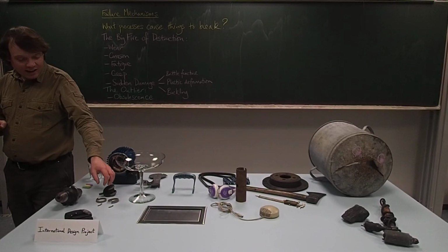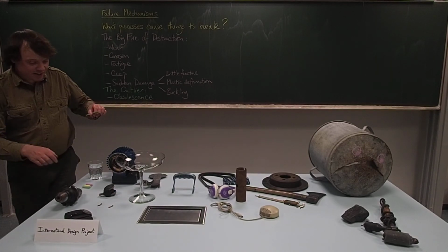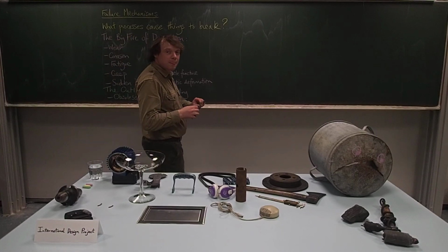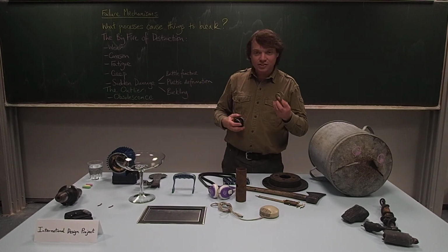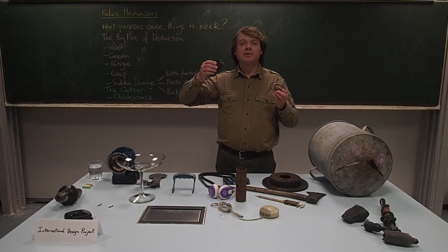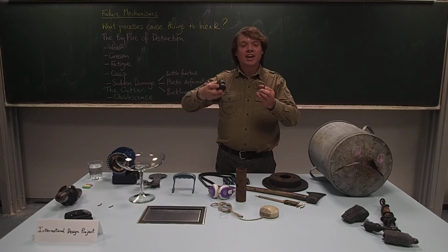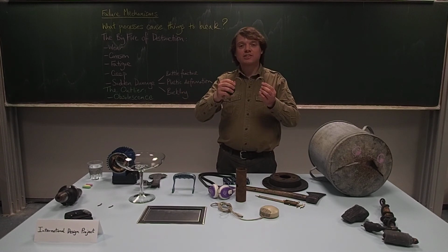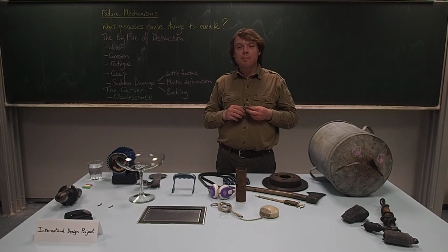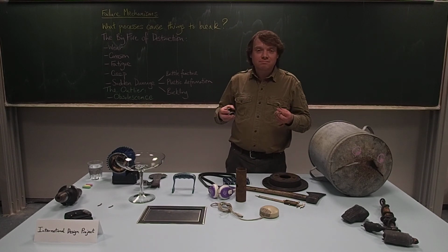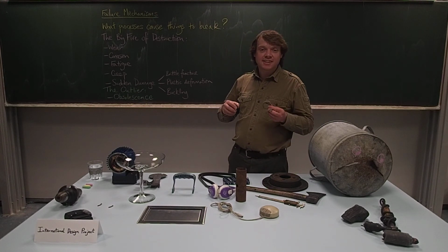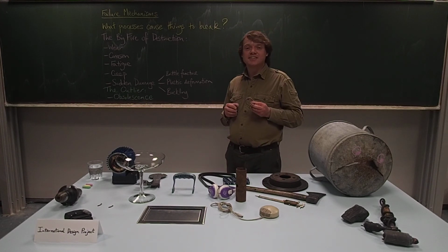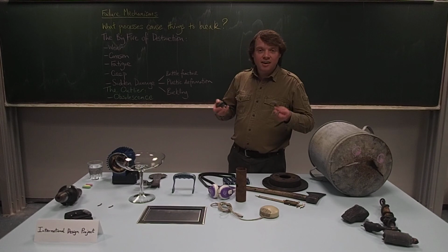This one here shows the perishing of rubber tires on an office chair. You can see these plastic wheels on the office chair caster originally had these little rubber tires. Over time the rubber perished, so it developed crosslinks between the polymer chains, it lost its resilience and its elasticity, and it cracked and fell off.